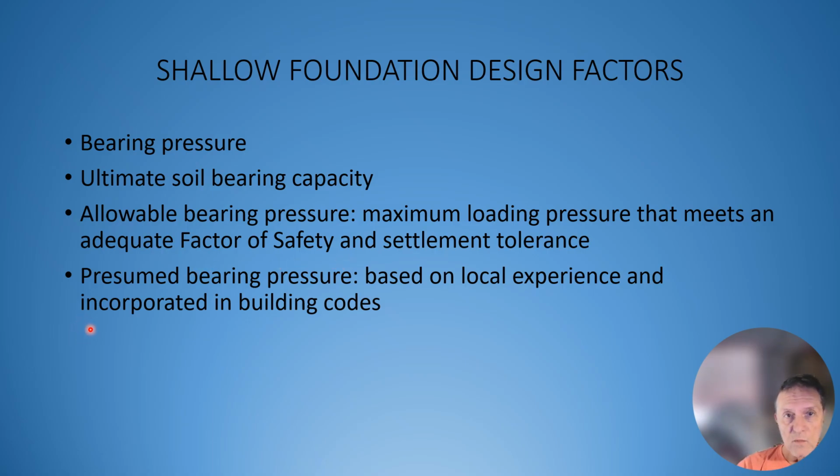You may have presumed bearing pressure where you're familiar enough with the local soils, local rock, the building codes that you can design based on assumptions, although it's always recommended to investigate a property by drilling borings or excavating trenches and taking samples and testing those in the lab.